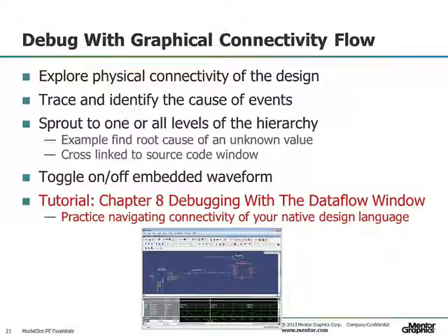So to augment debugging with waveforms or source code window with annotation, we also have a graphical interface so you can explore the connectivity of your design. You can trace and identify the cause of the events, for example chasing an unknown. You can sprout to one or all levels of the hierarchy, either forward or backwards, and again they're all cross-linked.